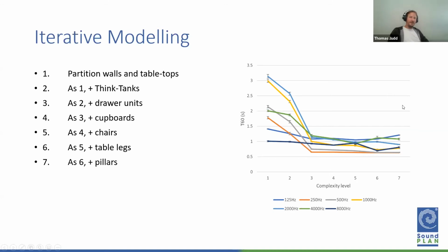And physically, the way we understand that is when you hit a sort of threshold level of scattering. Bear in mind, again, this situation is one of those acoustic ceilings. Hit the threshold scattering and you've got enough to mix your sound field and start sending stuff into those vertical directions that you kind of miss before. And once your sound field is naturally mixing itself, then not very much after that happens. The acoustic ceiling is being sampled in a realistic sort of a way.